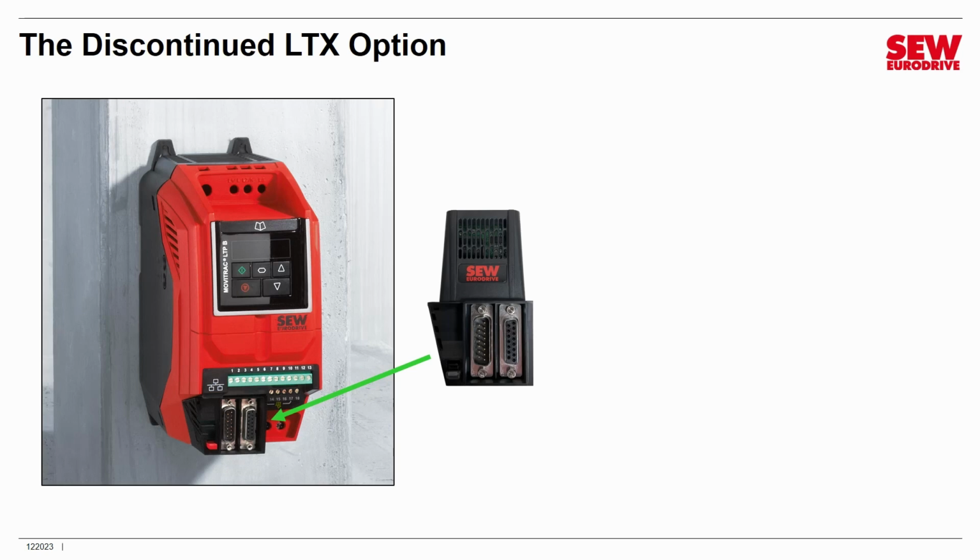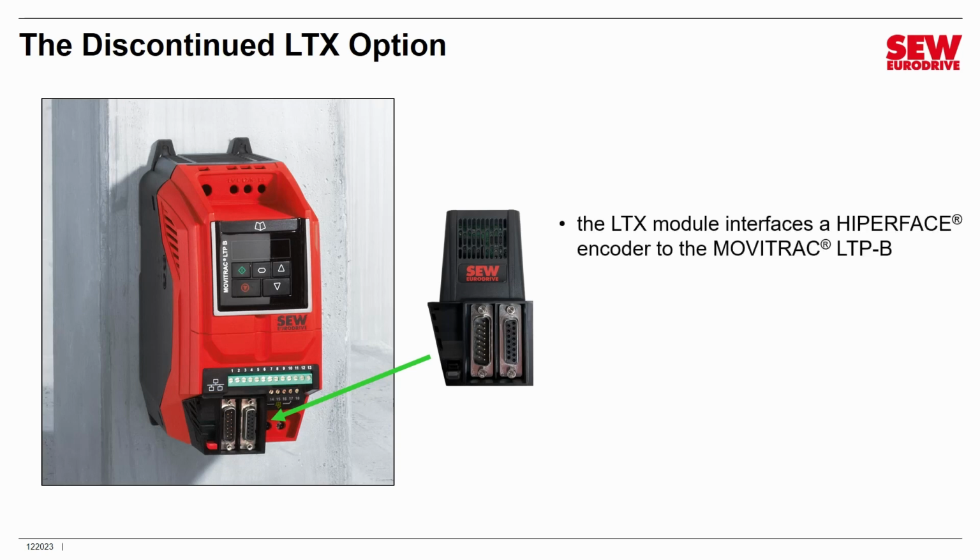And what it is, is a hyperface type encoder interface. It allows you to connect up a hyperface encoder equipped motor. This is something SEW Eurodrive offered in the past. It is discontinued. We no longer sell it, but you may find these out in the field. And if you do, I want you to know what they are. So that is what this option is.